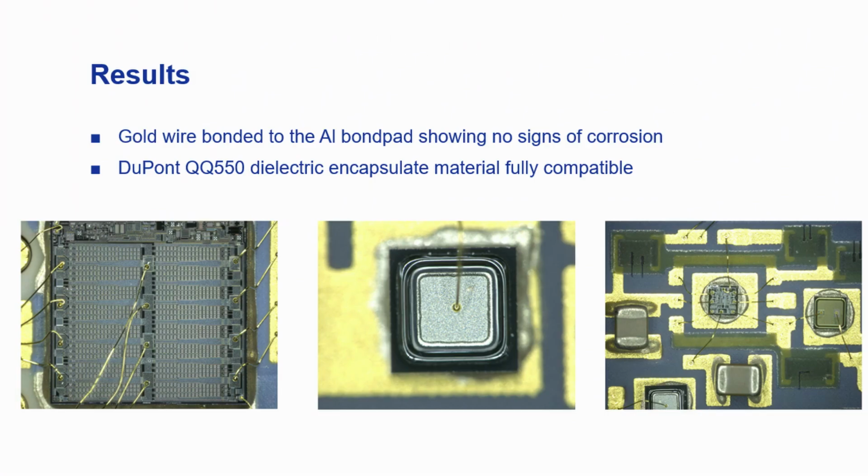It was a very critical customer with high product and high requirements. So we decided to focus on testing different cleaning chemistries, and we were able to narrow down to a pH neutral formulation, which was able to successfully remove the flux residues, as well as add enough corrosion inhibitors in its formulation to completely avoid the formation of galvanic corrosion related failures.